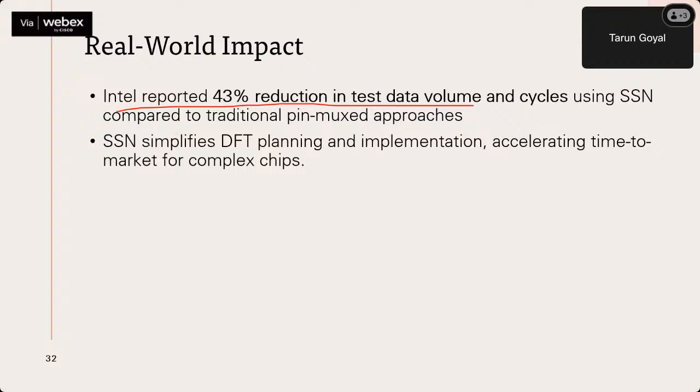Similar kinds of results are there for other SoCs also, benchmarking the industry standard, and we are capitalizing on a similar test reduction of 30 to 40% easily in our environment also for auto. So in a way, our test cost was increasing, which came down by using this SSN infrastructure and bringing more test packets at higher speed, without changing the core-level frequencies.